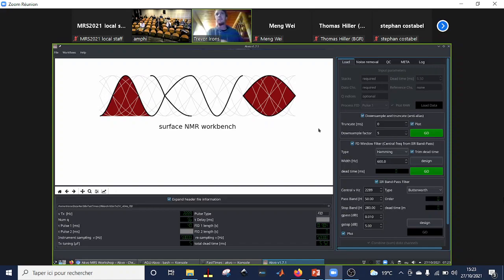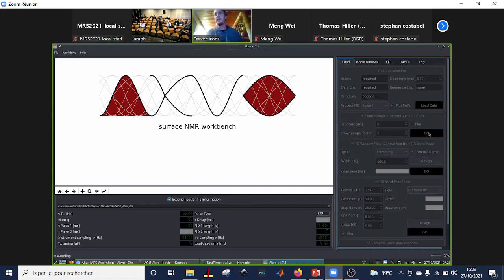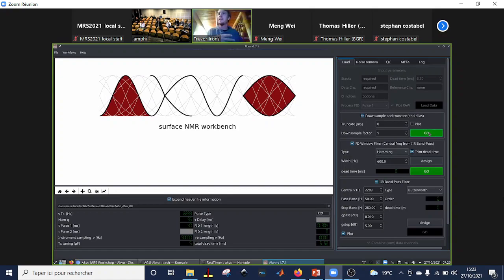The next step, you can do these in any order, but as a natural progression is to downsample. And the plotting takes quite a bit of time. So if you don't want to play with that data, you can click the plot, and here it's going to downsample the data because the GMR data is quite a bit oversampled. This functions as an anti-alias filter as well.